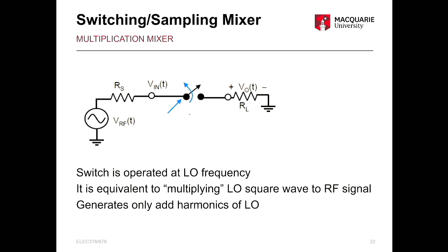But one of the signals was the LO signal, the other one was the input RF signal. But the LO signal can be a switch, and still you can obtain a mixing action there. That switch will operate at the frequency, it'll close and open at the frequency of LO. Okay, so that's when you get the IF frequency at the output.